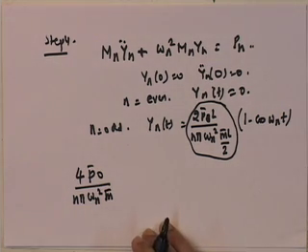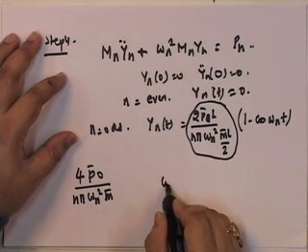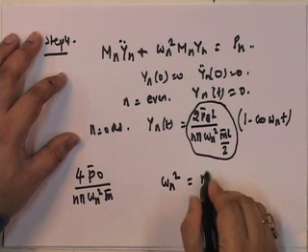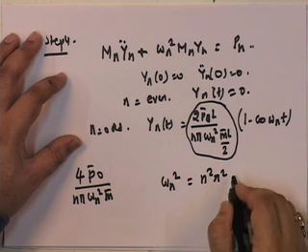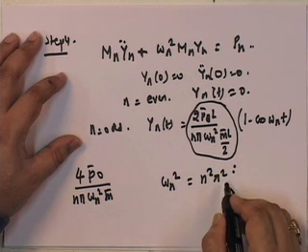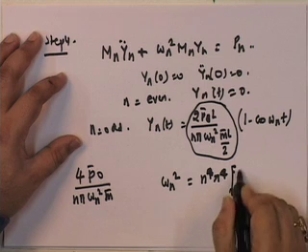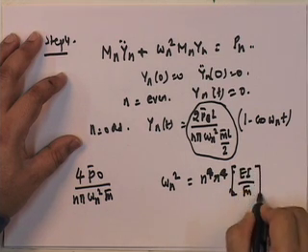Okay. Now, let us see what omega n squared is equal to. Omega n squared is equal to n squared pi squared, right, into, sorry, is n fourth pi fourth into E I upon m bar L fourth.